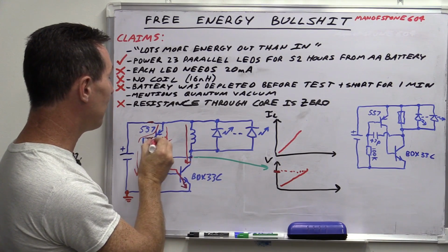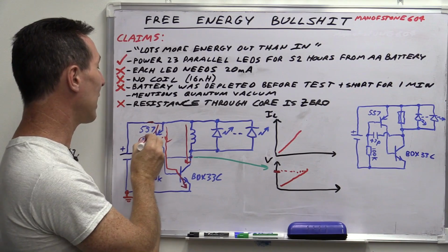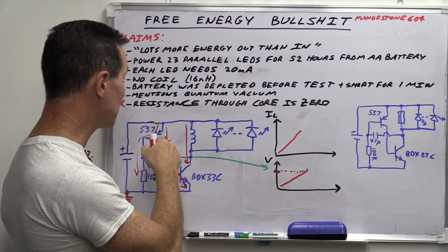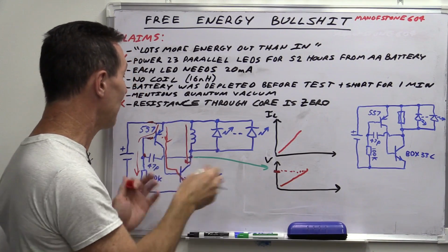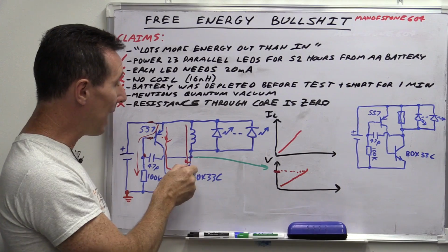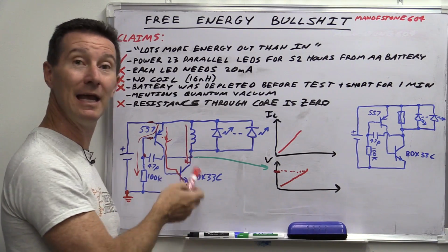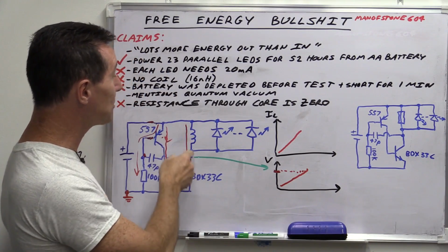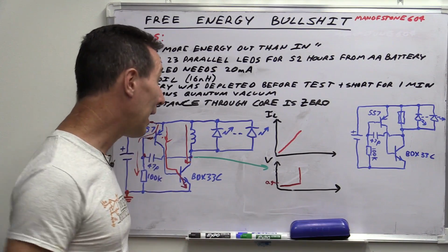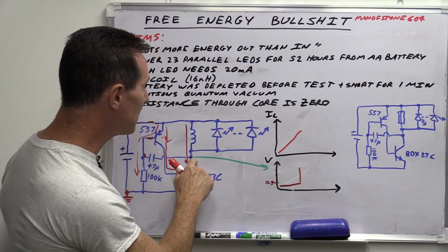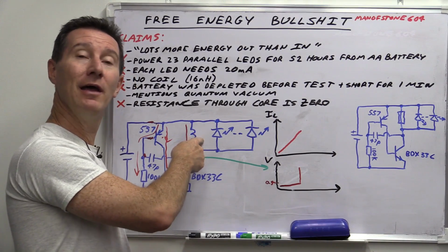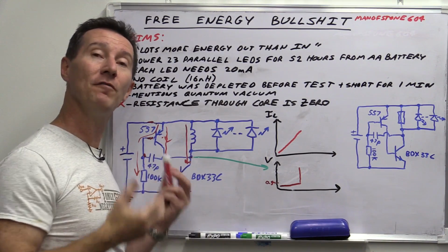What happens when this transistor no longer has enough base emitter voltage there? Well, it's going to switch off. What happens when that switches off or starts to switch off? It all happens very rapidly. So when this transistor here switches off, it deprives the base current of this main charging transistor down here. And what happens? Wham! It snaps off and bingo, we're now in a different state. And what happens at this point? Aha, here's the magic. The voltage at this point is going to suddenly shoot right up. How far? Well, it depends on the collapsing magnetic field of this inductor here.